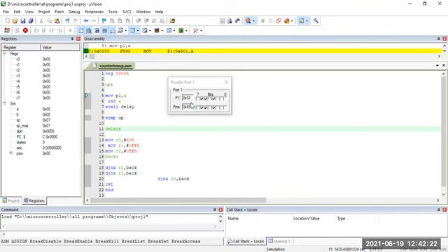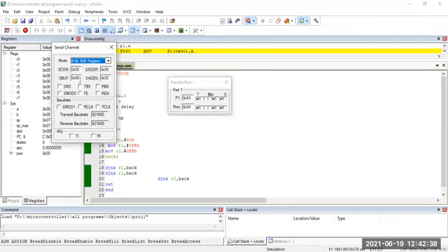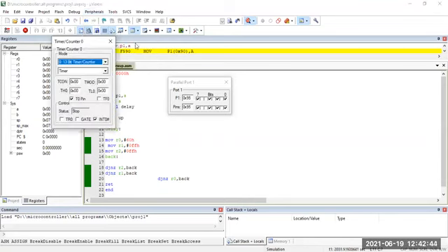Similar to the timer, whenever you are executing the timer programs, you just keep observing this one. You have to check these timer 0, timer 1, timer 2. In the same way, I'll teach serial communication also. In that case, you have to take serial communication and observe the values here. For timer values, you have to observe here. TCON value will be there, TH value will be there. All the values you have to observe here.